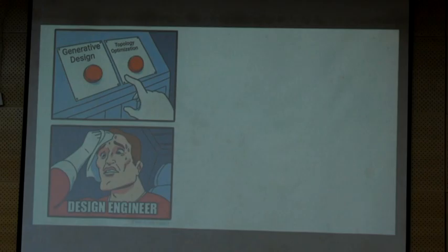If it exceeds 2, we can reject the sample. It should also not go beyond the yield strength. And the deflection, the optimized geometry should not deflect. These are the constraints we are fixing, okay.